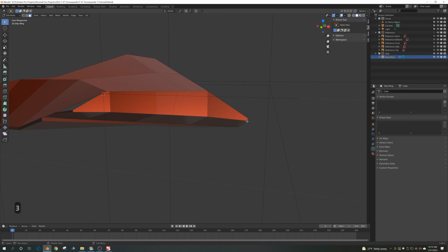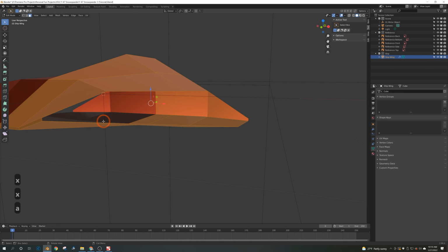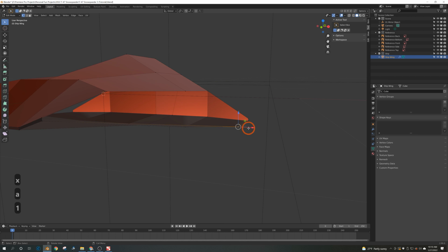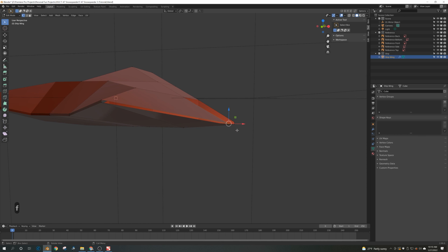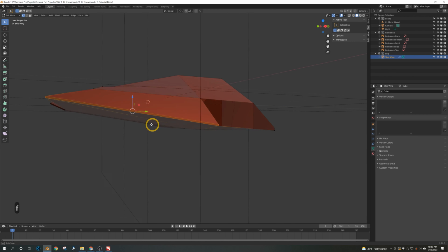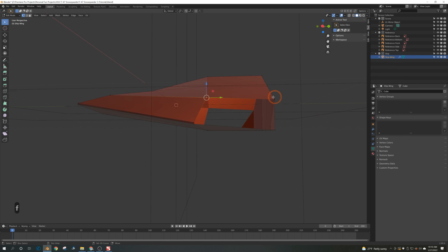Well, all right, here's what we can do. Delete that face. Delete that face. One, all. This one. Okay. Extrude that up. All right, select those two. F to join them with an edge. Select these four. F to join those with an edge. Select these two and those two. There's our edge.